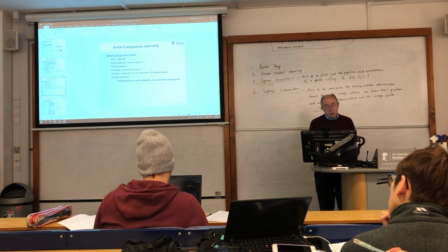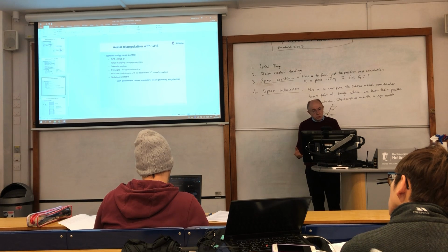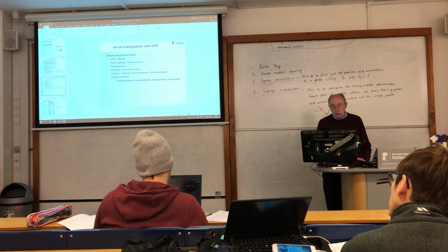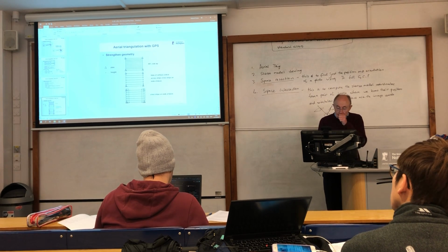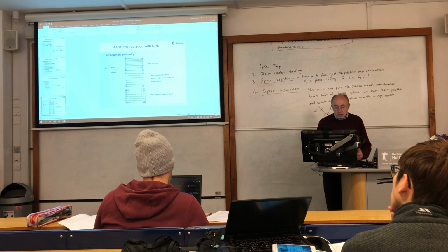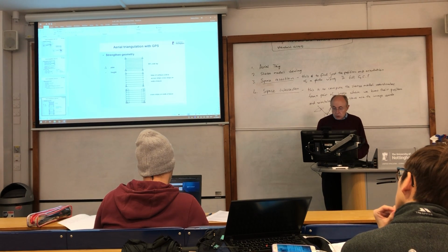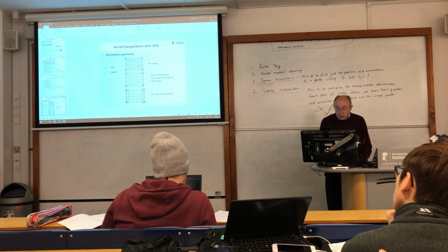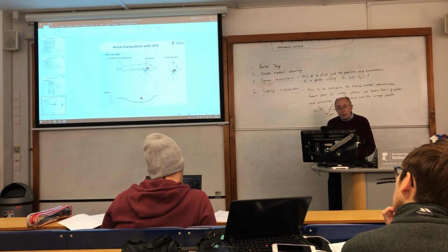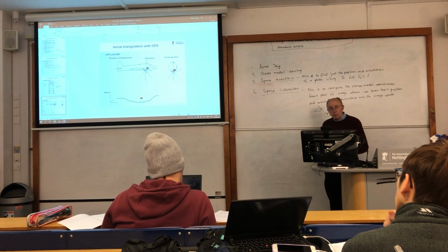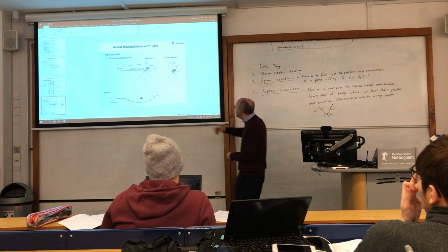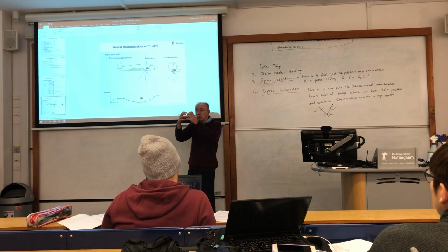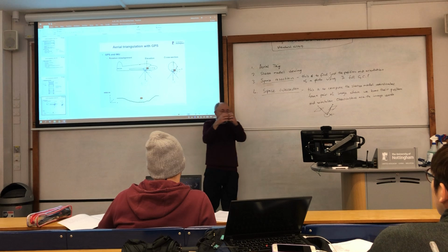If you remember, the other issue is the datum. We're going to work in GPS coordinates, which is WGS84. We need to transform to the map projection. And we could end up with some instability in the solution, which requires us to strengthen the geometry. And we need a misalignment rotation matrix, because we cannot bolt the inertial measurement unit onto the camera so that we know exactly the relationship.